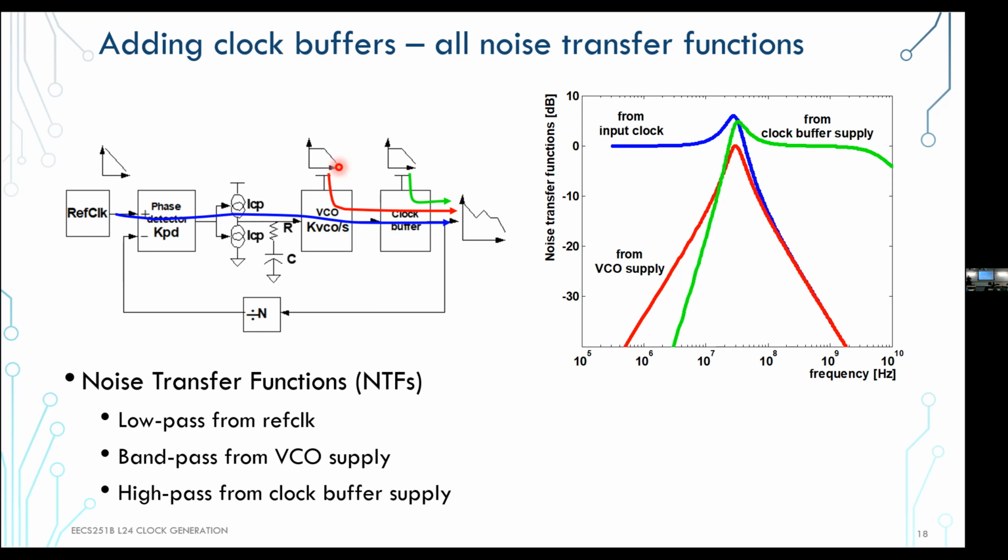And as we know, logic transitions with some random activity. So you're going to get some bursts, and then some more bursts. I can't draw it, but you could do a Fourier transform of that and see what spectrum it gives you. It's going to be pretty broadband, but eventually it will roll off. And of course you have decoupling cap and all that, but definitely you have something like this happening, and similarly on the clock buffer. So you can use these kinds of estimates and essentially figure out what your overall noise transfer function is.